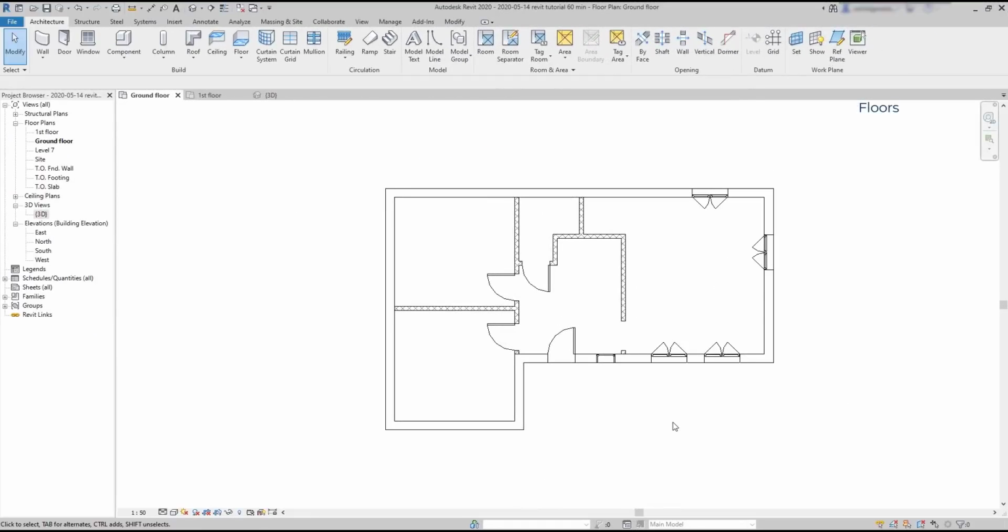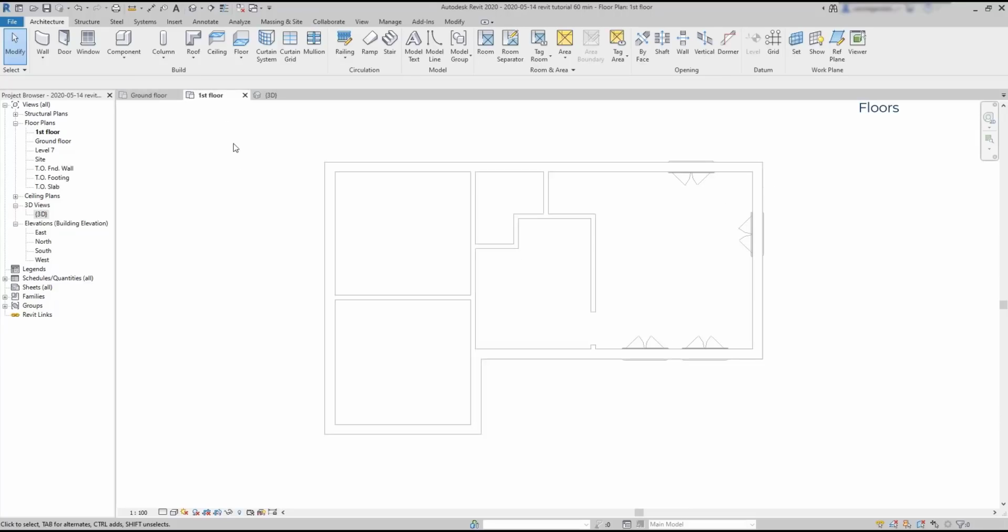Now, let's add the floor also to the first floor. It's easy. I switch to the first floor tab and everything that is shown here are the walls and elements from the floor below. And that's why they look transparent. If I open a selection area covering everything, nothing goes onto the selection. On the other hand, this can be very useful to draw elements in this floor, like the floor itself.